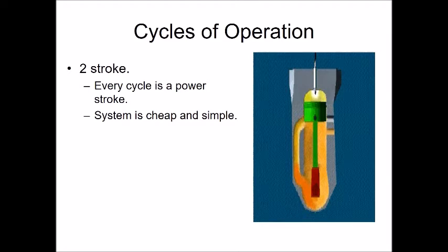But thermodynamically, in terms of our cycles, it's not a four-stroke cycle. You might have learnt about four-stroke cycles, possibly in high school, so you may remember suck, squeeze, bang, blow, which are the four colloquial terms for the four-stroke cycle. But a two-stroke cycle is something quite different. It actually does two of the processes almost simultaneously. It's a bit more homogeneous, this cycle. Things tend to happen more gently, and at the same time, whereas the four-stroke cycle is much more discrete and ordered.